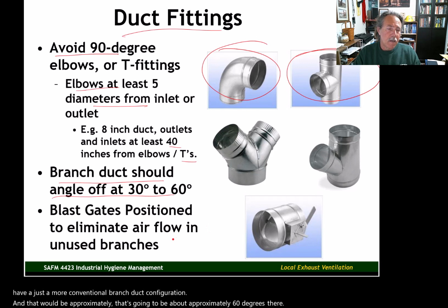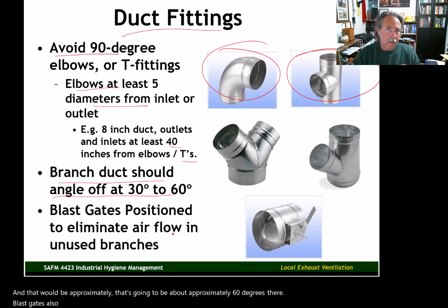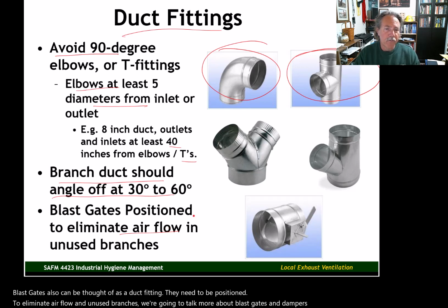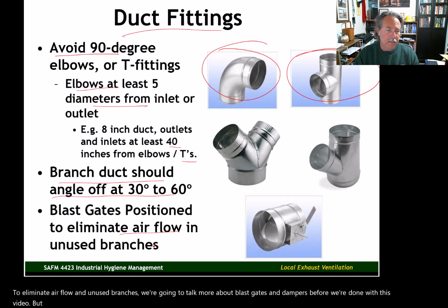Blast gates also can be thought of as a duct fitting. They need to be positioned to eliminate airflow in unused branches. We're going to talk more about blast gates and dampers before we're done with this video, but that's the purpose of a blast gate, to control airflow through the system.